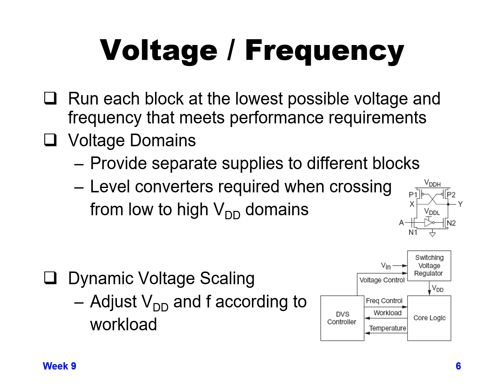And then the other thing that you can do is, instead of just having voltage domains that are at different values than each other, you can dynamically adjust your voltage in a given domain. So maybe you might have it at 0.8 volts at a period of time where you're doing something that doesn't demand a lot of performance, and then have it ramp up to 1 volt or 1.1 or 1.2 volts at a time when you know you need extra power or extra performance coming out of it. So that's called dynamic voltage scaling, where you can adjust your voltage and your frequency depending on some critical workload that comes in.